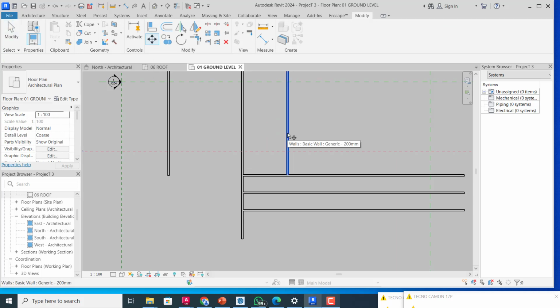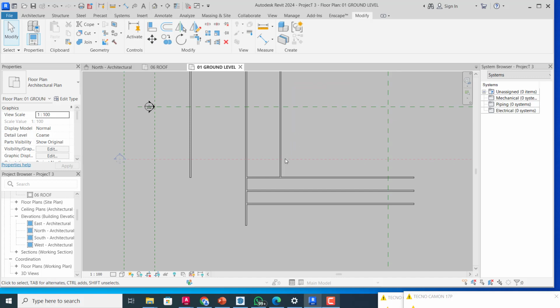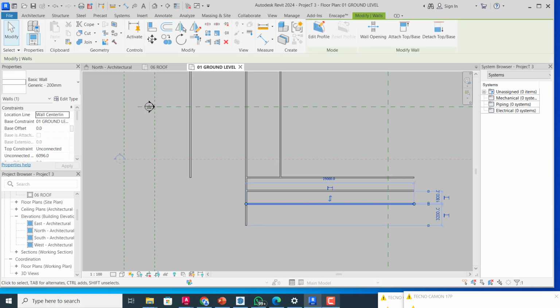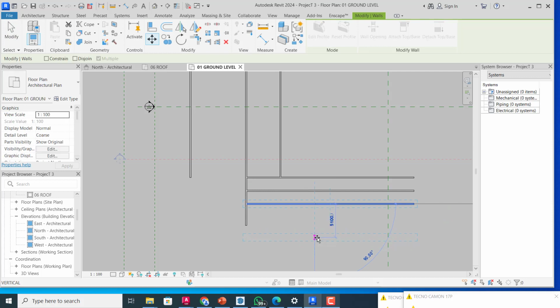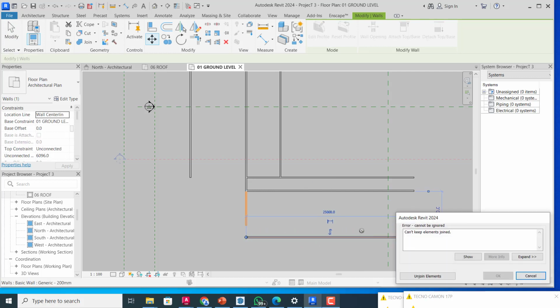Similarly, that is the best way to move your tool. If I want to move this as well, I will just select it and click on move, and then I will just hover my mouse along the direction. I can also specify the distance to where I want to move my tool.